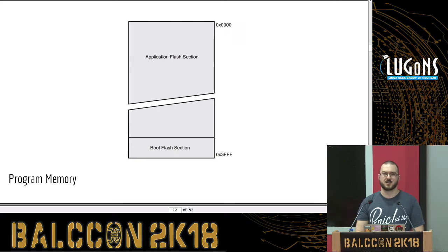Because you might not want to have a firmware writing to the program memory all the time and waste your write cycles, but rather have it done by the bootloader. And you can do stuff like encrypting or decrypting parts of the firmware with the bootloader before you actually run it.